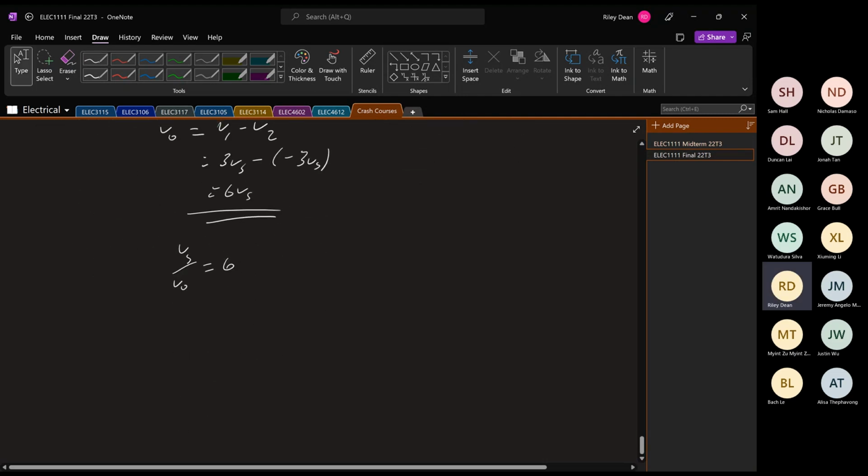And this actually raises a very interesting comment about things that we can do using op amps, which is we can make a much larger load be driven just by using some circuitry in between. Because this output voltage at the speaker is 6 times the size of what we've input, which is very handy to use. Also, this is backwards. That should be V0 on Vs.